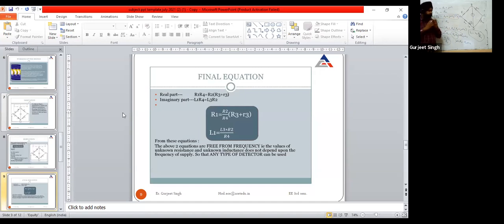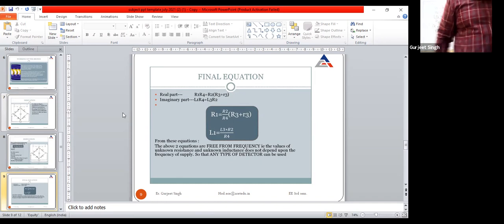But in most books, they have neglected this small resistance. When you solve the numerical part of the Maxwell bridge, the examiner generally gives this R3 value also. In the numerical part, they have written values like this 3 Henry, and the value of R1 is 10 ohm. In that case, you have to consider this value, and simply modify the equation of the Z3 impedance by writing the small resistance R3. So this is the Maxwell inductance bridge.